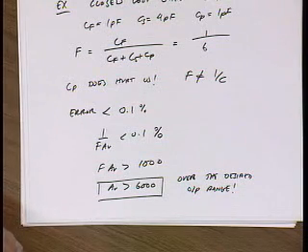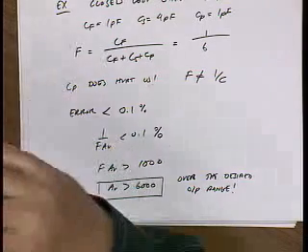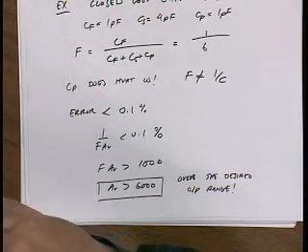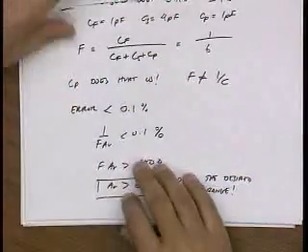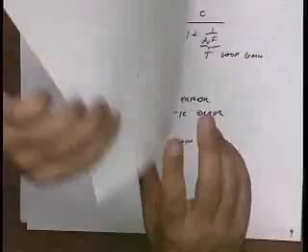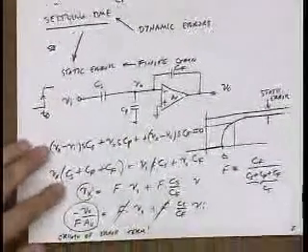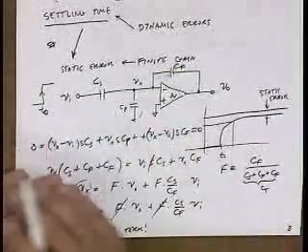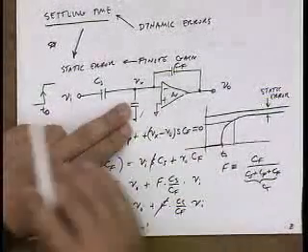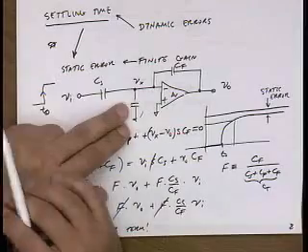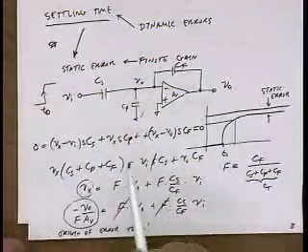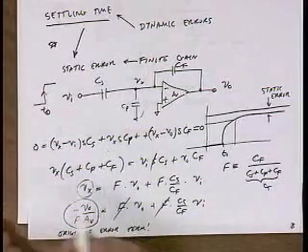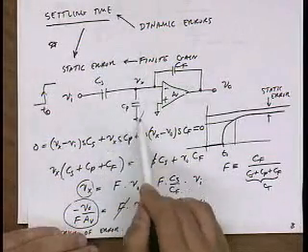Okay, you have a question? Could you explain that portion a little bit? F not equal to 1 over C, what you said. Okay, so the idea is that in this amplifier, the closed loop gain does not depend on CP. Closed loop gain is just minus CS over CF. But in doing this calculation, and in fact we saw this for the noise as well, this factor F is important. And F is a function of CP.